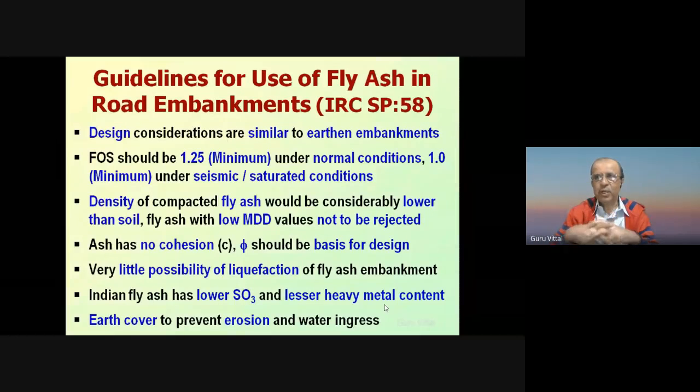This liquefaction during an earthquake we can see in very fine sands and in silty soils also. Fly ash has a particle size similar to silt, similar to sand, as I told you. So will this material liquefy? An embankment constructed using fly ash will not liquefy. That is because for liquefaction to occur, I told you the different conditions to be satisfied. First, of course, it has to be a silt size material. Fly ash may be a silt size material. But the next condition, it has to be in a loose state.